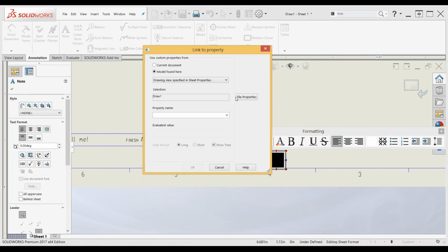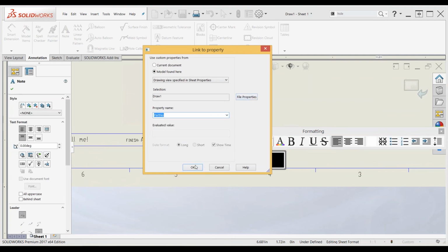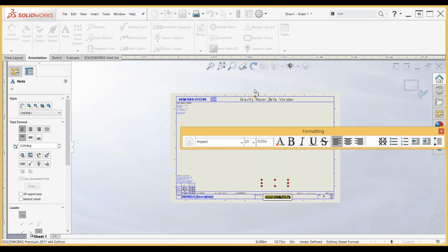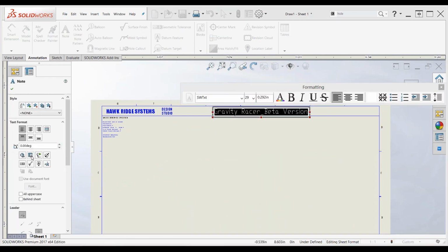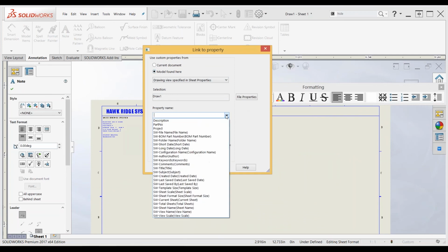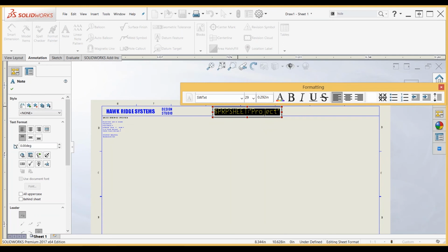So this drawing that I have here and some of the stuff I need to manufacture, I'm going to have to outsource internationally. So I'm going to have to send some to Asia, some to Europe, some to South America, and they use different projection styles. So what I'm going to do is add just an angle of projection box just so I can really clarify which formatting I'm using.